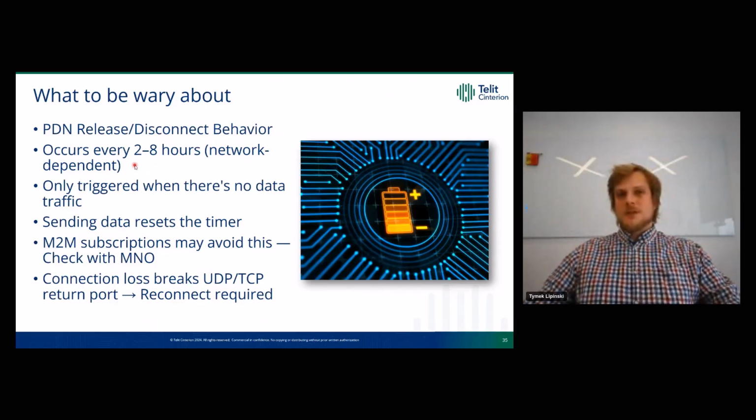What will the modem do in this case? It will reset its connection, search the network again, and attach. And the network will allow it because it's a new activation of the PDN. This only happens when there is no data traffic from or to the modem. Sending any kind of data will reset this timer, so it gives us another chance.